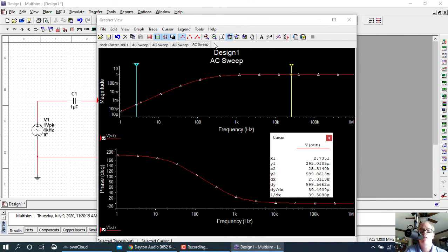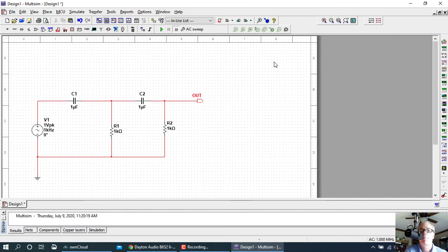It's called sweep because the way this works is it actually starts out, and does all the hard work for you, testing at the low frequency, and then it changes to the next frequency, then the next frequency. And so it's like a sweep. It starts low, and comes up high, sweeps all the way up to the high frequency and then starts over. It does that over and over, and then we get our measurement. So in case you were wondering, that's why it's called an AC sweep. But it is a spectrum view and a spectrum analysis of what's going on with our circuit.